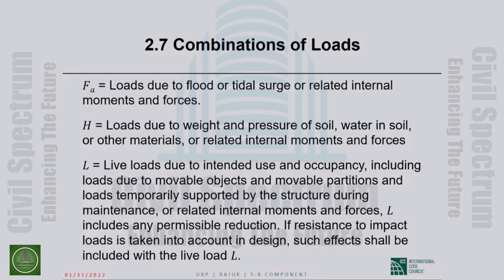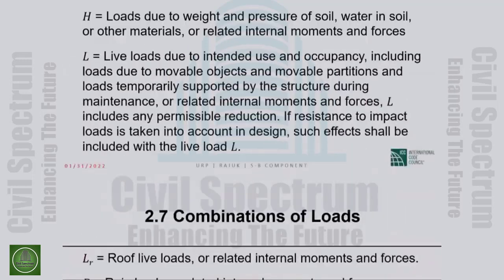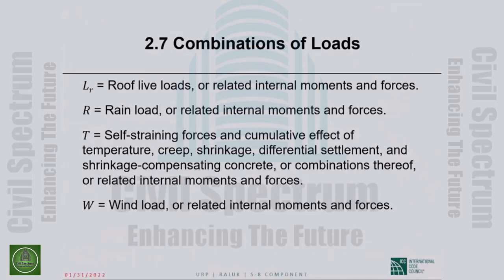Okay. L, live loads. L without a subscript is floor live load. L sub R is roof live load. Capital R is rain load. T is a difficult term. It is T, I think, stands for temperature effects, but it is the best way to describe T. It is the effects of restrained volume changes.